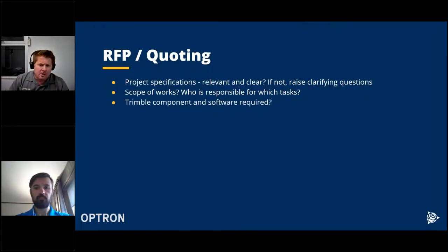So which Trimble components are we using for this installation, for instance, and what software is required? So if it's an existing customer, you will only perhaps have a couple of node licenses and maybe software warranties that you need. If it's a new customer, obviously you need to decide on which version of T4D they require. If it's only geotech equipment, you can do Trimble Geotech. If it's more than that, you might need to look at T4D Advanced and such.